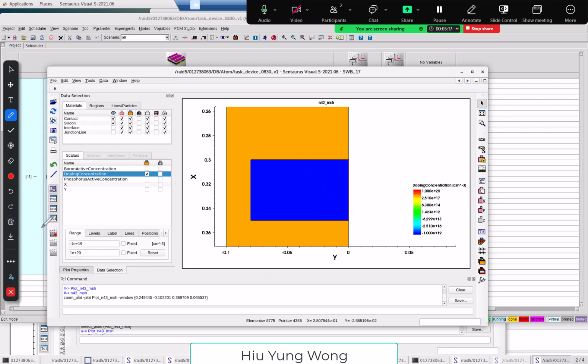As a result, we would like to make this one shorter. We don't need to cover the whole region because it doesn't matter, right? What we're relying on is that this contact applies a potential to this P region, and this is conductive. Whether you have this contact here or not, it should not change too much, particularly because we don't have a huge current flowing here. Even if we increase the effective resistance a little bit, it should not affect the result. Okay? So this is one thing we need to fix.